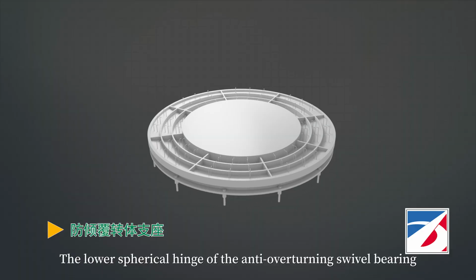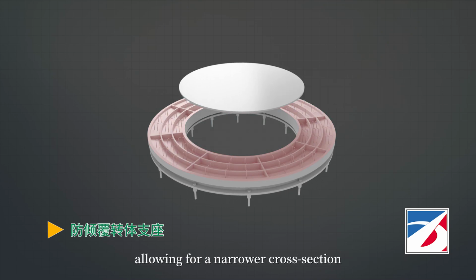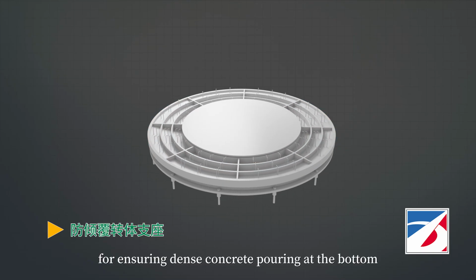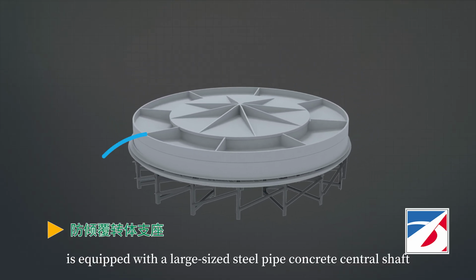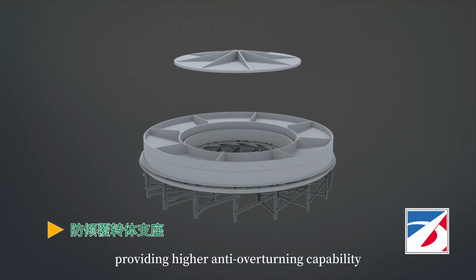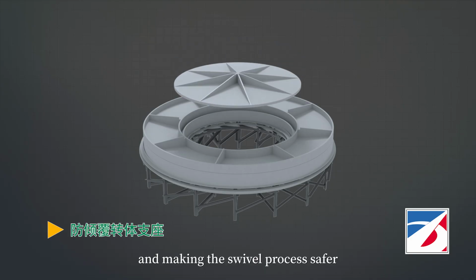The lower spherical hinge of the anti-overturning swivel bearing is hollow and circular in shape, allowing for a narrower cross-section under the same load-bearing capacity, which is beneficial for ensuring dense concrete pouring at the bottom. The lower spherical hinge is equipped with a large-sized steel pipe concrete central shaft, providing higher anti-overturning capability and making the swivel process safer.